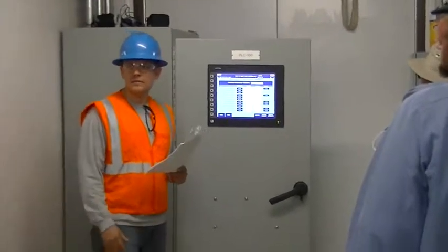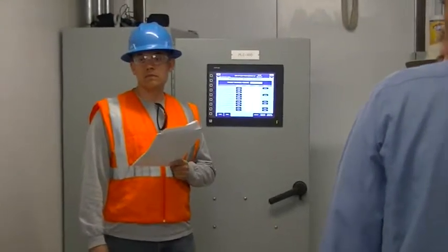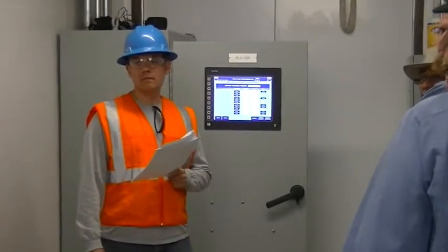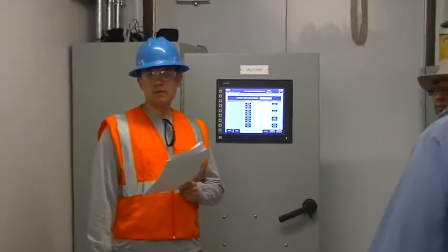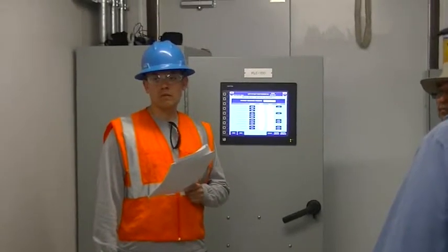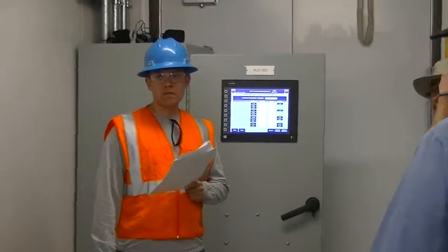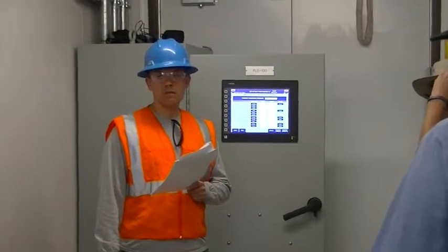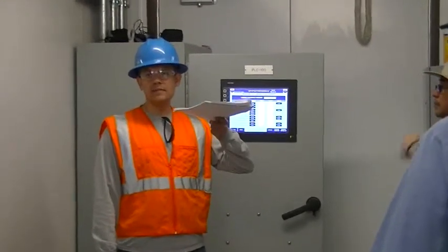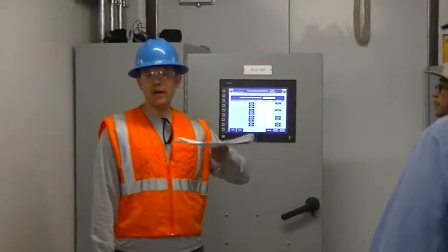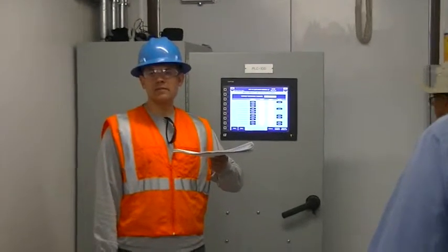Any questions on that? So you're saying that when the pumps are operating and they're trying to maintain pressure, at some point they'll pump up to 70 psi before they shut off. Correct. So that means your system is getting up to 70 psi at that point, and then as demand, I guess, takes over, it'll slowly bleed off that pressure. Yeah, so if you hit that 70, it'll shut down, and then it'll come back on once it hits that 60. And then it'll ramp back up and try to maintain the 65.